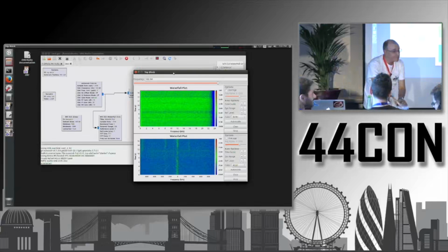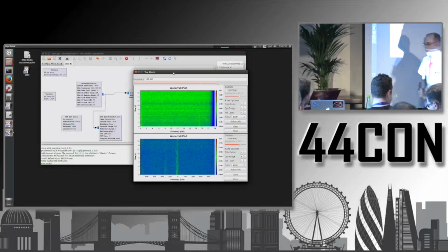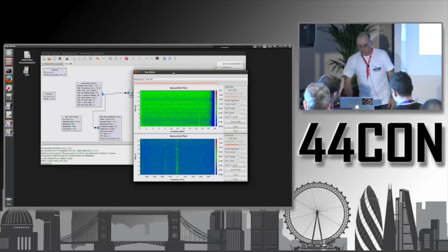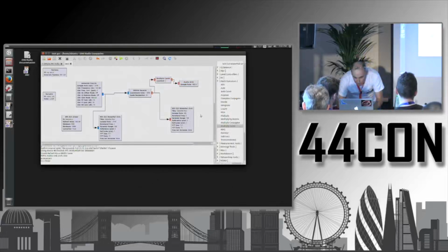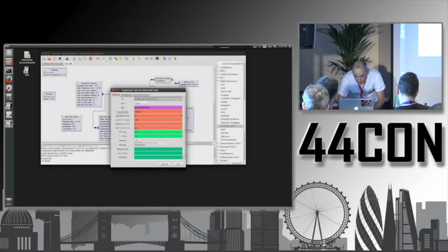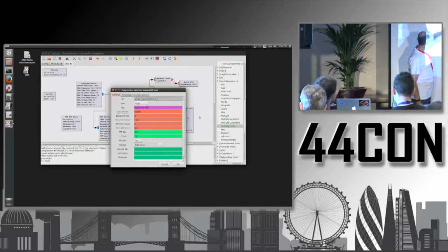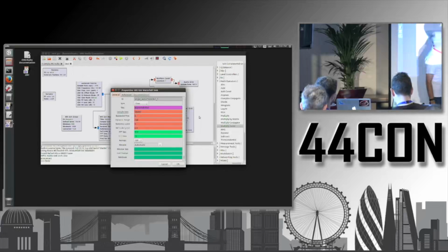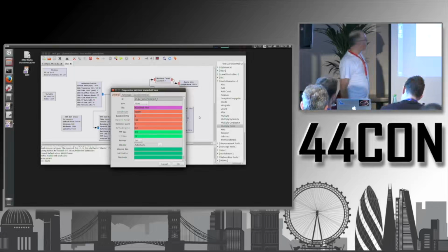Could you remind me of the configuration for the phone? Yeah. So let me stop this. I put in the waterfall sink, I change it to float, and then the sample rate, exactly the same sample rate as the audio sink, 48 kilohertz.